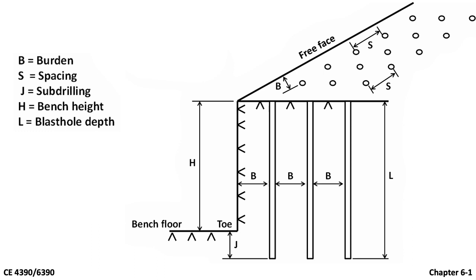In this example, the effective depth or the bench height is not given yet, but we know the length of the hole, which is 20 feet. As noted earlier, the bench height is typically equal to 90% of the length of the hole. Let's use H equal to 90% of 20 feet.